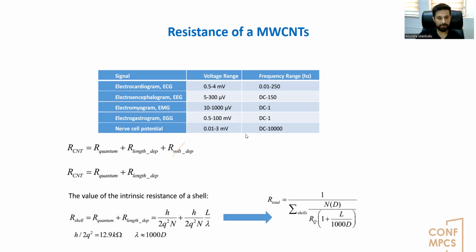The related electrode that we're talking about is a biopotential electrode, of course, so electrophysiological signals with low amplitude voltages are applied to the carbon nanotubes on the electrode. As seen in the table, since the voltage range of biopotentials is between 5 microvolts and 100 millivolts, the low voltage excitation condition of carbon nanotube that was stated in the previous slide is now provided.